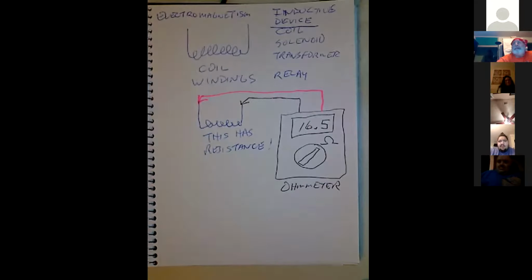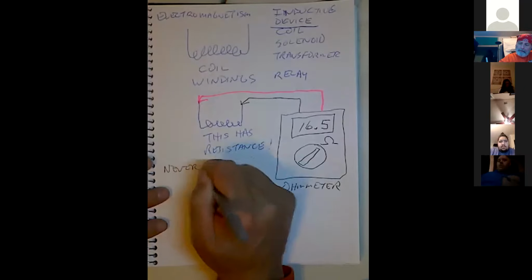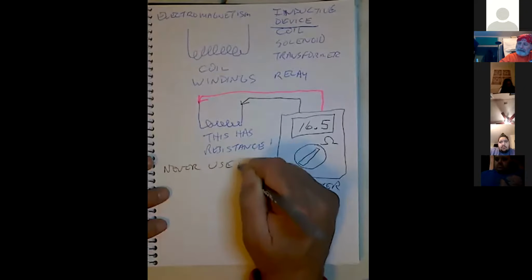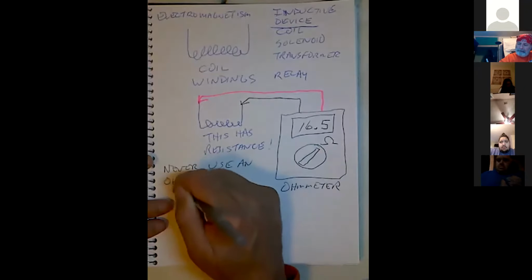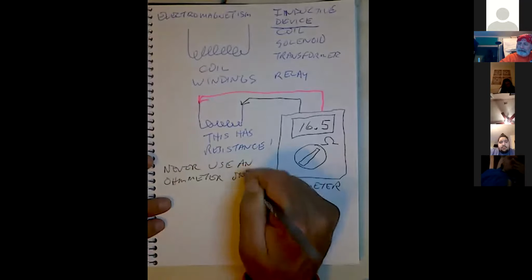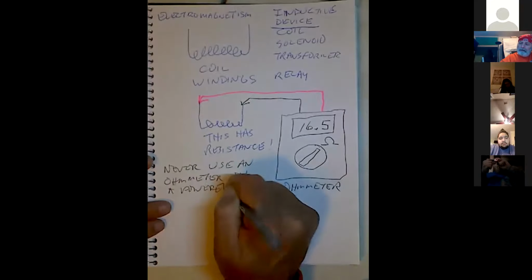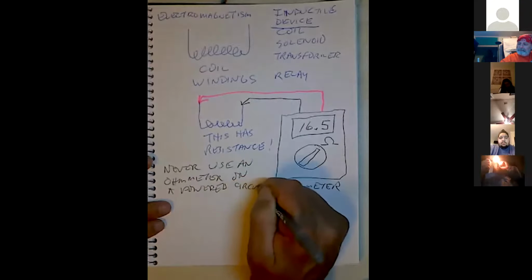That's right. I'm using an ohmmeter, right? What's the rule on using an ohmmeter? Disconnect it from any power. Never use an ohmmeter on a powered circuit.